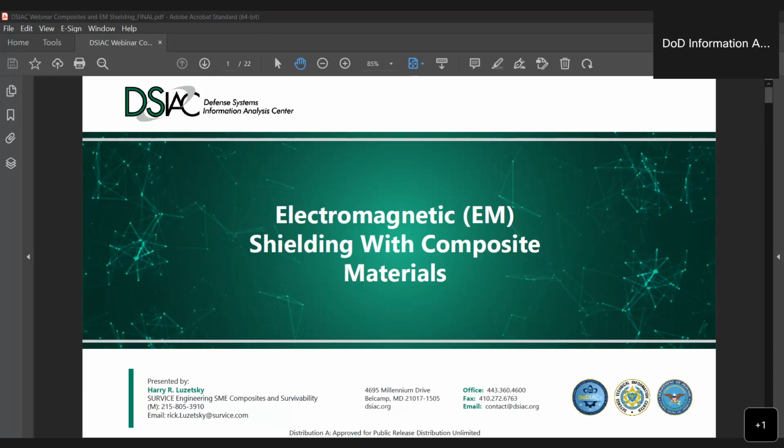No. What the EM shielding will do is reduce the electromagnetic output for those systems that actually detect a vehicle based on electromagnetic output, if you will. The answer there is yes. But will it reduce it from an aspect of radar signature? The answer is, I want to say no, but I'm going to say not necessarily. We currently have a program where we're looking at that. As it turns out, the electromagnetic shielding that we've done works almost as a perfect ground plane. So we're looking to see if we can now build on top of that to get a reduction in radar signature, and still maintain the electromagnetic shielding.